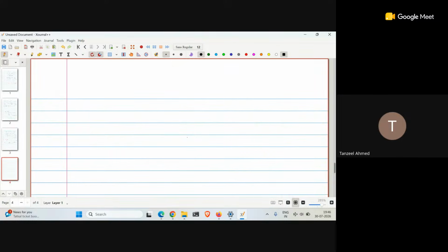The optional thing is that somebody can set up an LED circuit, but I don't want to mandate that. So basically what you do is set up the output pins QA, QB, QC, QD, and you connect them to LEDs, right? This is an LED, bad drawing. So let me do like this. Yeah, that's an LED. And definitely put up a series resistor over here. Well, we have not talked diodes in this lab course yet, so I won't really emphasize this. If somebody has worked with LEDs before, then they are free to try this, but this is not really needed, entirely optional.